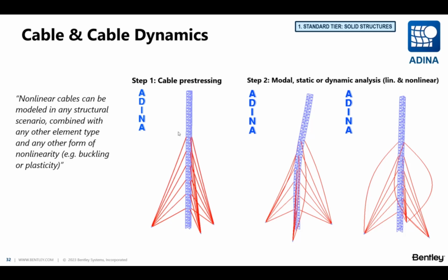Because then what happens is that the stiffness changes, the natural frequency changes, and that's how the sound of that guitar chord changes. So this is what happens on a cable-stayed structure. The natural frequencies and the dynamic response will certainly be affected by the stress on those cables. And this is the stress stiffening effect that we capture. Again, this is useful for all kinds of cable-stayed structures.